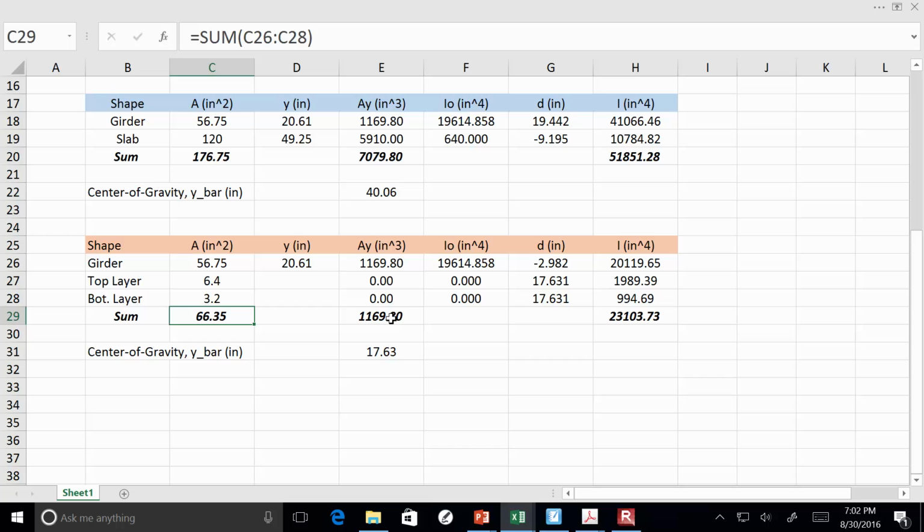All right? So let's deal with the top layer first. Okay. So keep in mind, let's sort of imagine this in our brains. We're going from the datum, which is the way bottom of that section, to where that rebar is, right? So let's imagine. We go up the thickness of the bottom flange, right? Then we go up that web depth, right? Then, if we go up the haunch, that puts us at the bottom of the deck, right? If we go up the structural thickness of the slab, that's the entire height of the section, right?